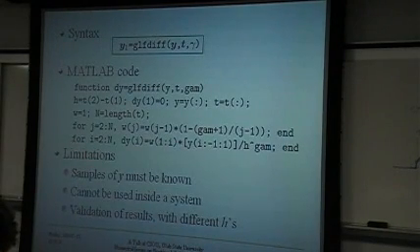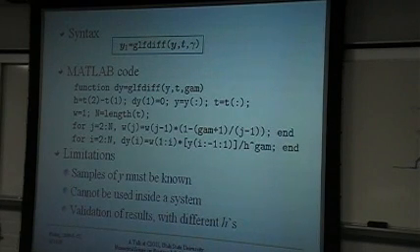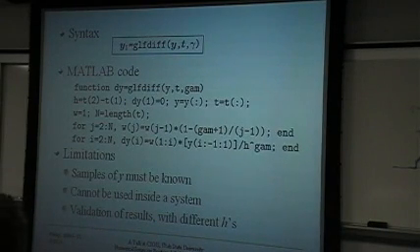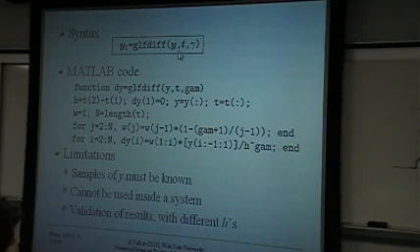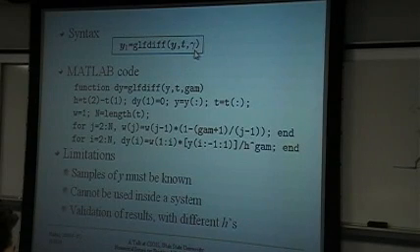So I wrote a function myself to calculate the fractional order differentiation of a sequence y, a signal y. We have some sample points in y, and we can call the function glfdiff with the y vector, the t vector, and we can specify the order. Then we can find the derivative of it.